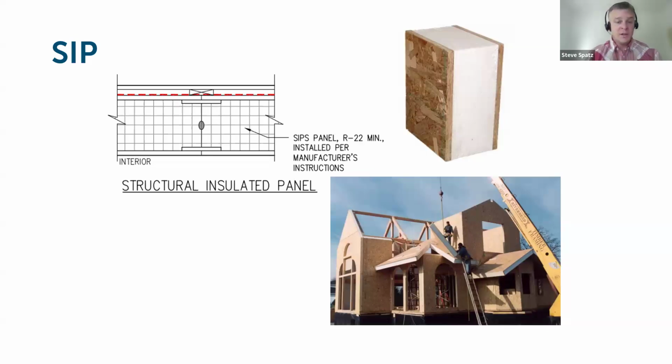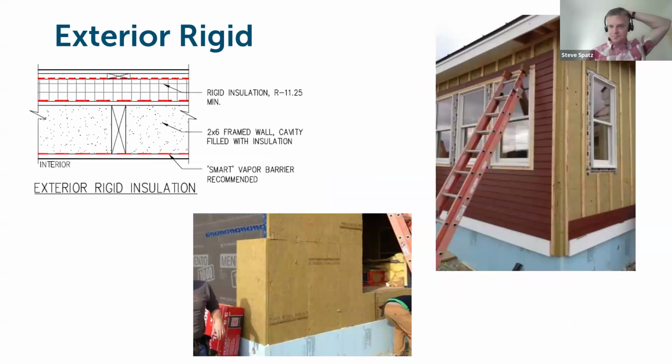But when used as a structural panel and engineered, you can have the entire wall and roof assemblies of a building built in a matter of days, and a highly effective continuous insulation structure built. But it does take careful detailing, a good manufacturer, and a good system for dealing with the joints and splines of putting the panels together to make sure that they're airtight and not vulnerable to moisture loading at the seams.